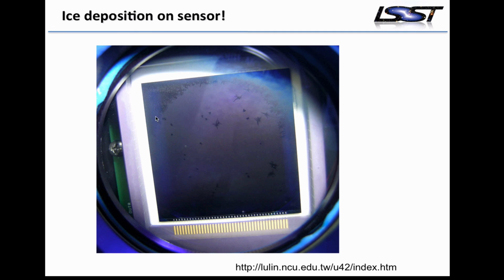One thing to be aware of is that if you cycle the Dewar that has the CCD in it in a way where there's ever an instance where the detector is the coldest thing in the Dewar, all the gases and water that are evolving off the Dewar wall or anywhere else that they were cryopumped will actually migrate to the surface of the detector and condense there. That's one potential origin of the ice crystals that grew on the sensor in this case.